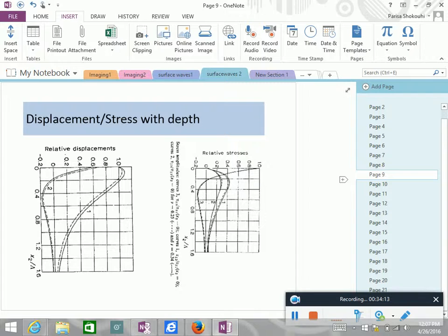Dispersion happens because the motion of a Rayleigh wave is confined to about 1 wavelength. So if you are probing with a lower frequency, larger wavelength wave, it's going to go deeper, and this wave is traveling through 2 materials. So its velocity on average becomes affected by 2 layers, right? But if it's small, it's within the small layer.